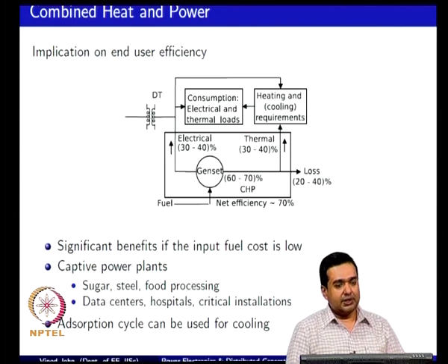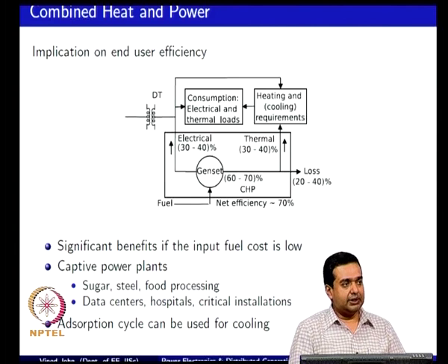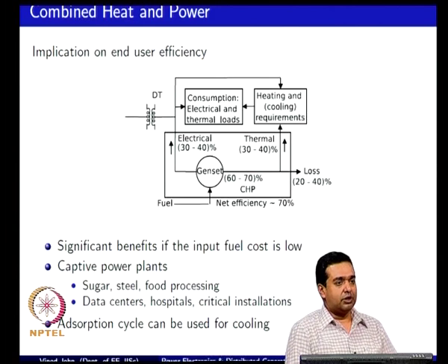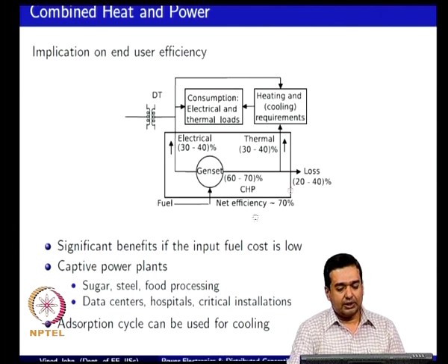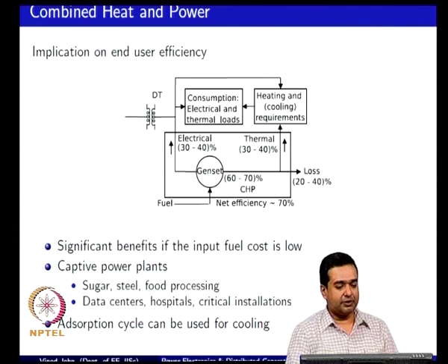Another appealing aspect of a genset is when you are not just looking at the electrical output from the generator, but if you can potentially make use of the waste heat that would invariably be generated from the engine. So, if you look at the efficiency of conversion from fuel to electrical, you are talking about numbers in the 30 to 40% range. So, if you are only generating electricity, you are just making use of this part of the energy that is there in the fuel, and there is a large amount of waste heat.